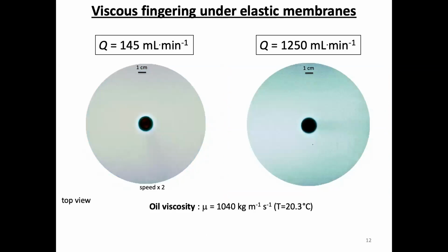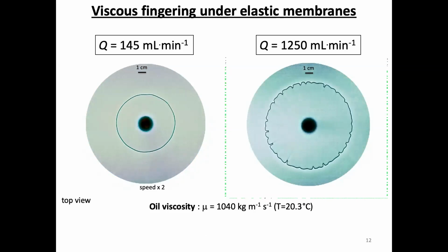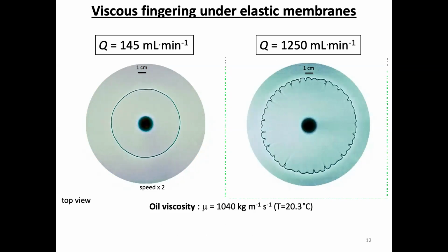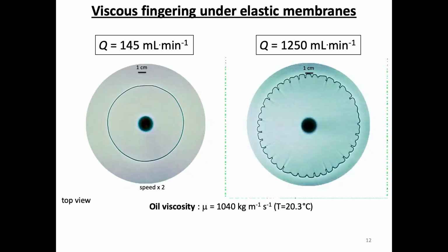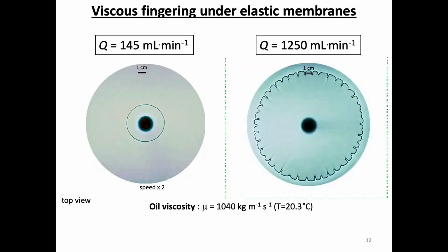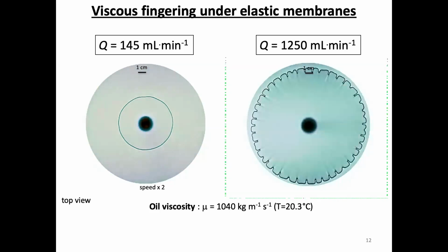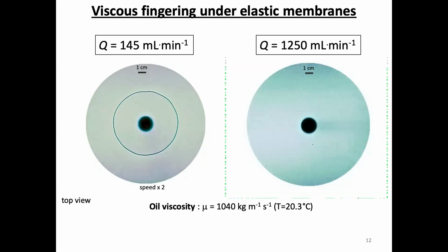Okay, that's not the whole story. The instability hasn't completely disappeared. It's still there, but you need to inject at a much higher injection rate. And then you will see the instability, and this is how it looks. It actually represents lots of little stubby fingers that are around, not much closer to where the interface sits, right? And these short and stubby fingers look nothing like those fingers that extended all the way to the injection point, right? So there is clearly some saturation length in that fingering that happens around the interface.